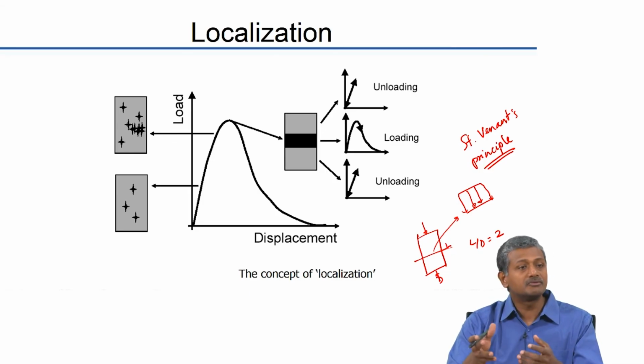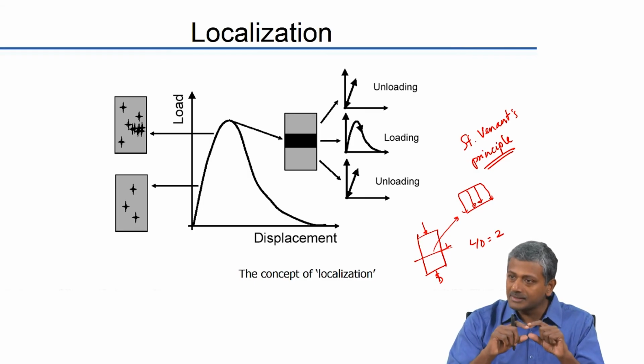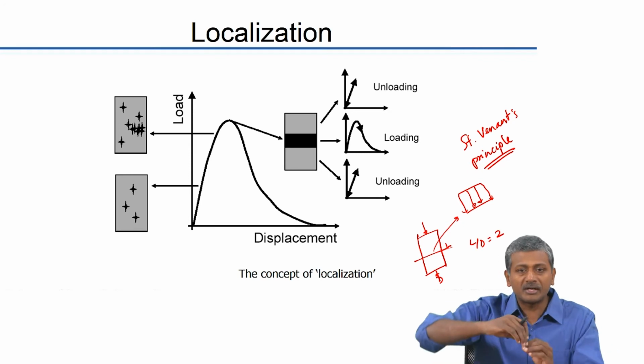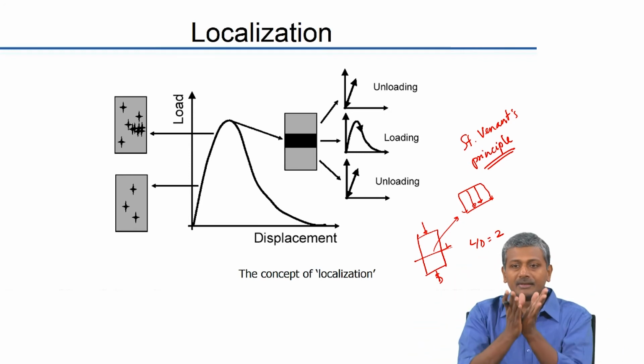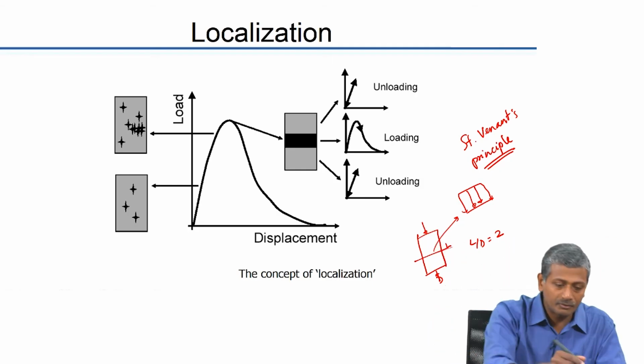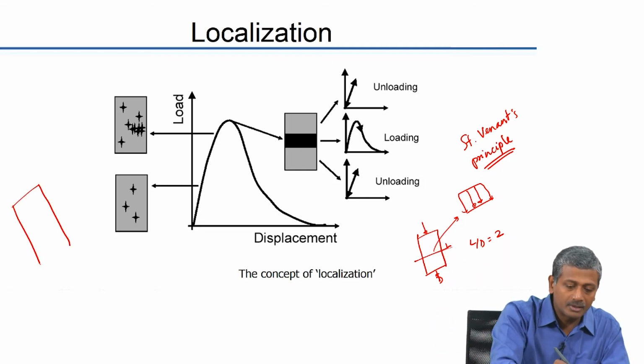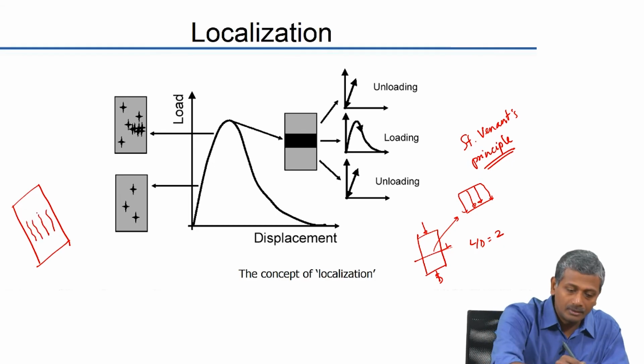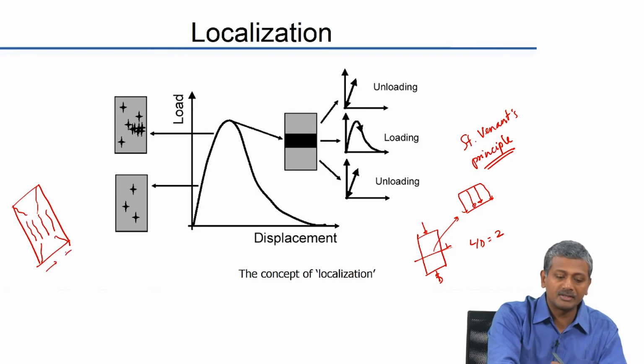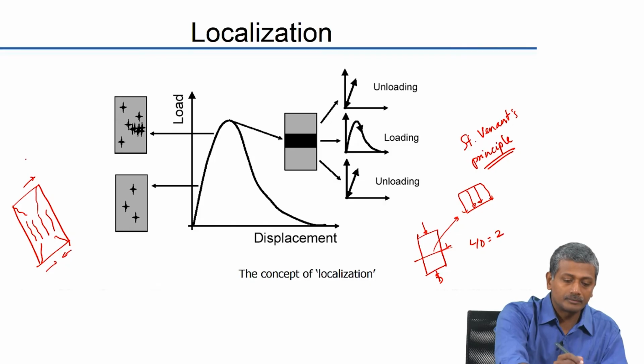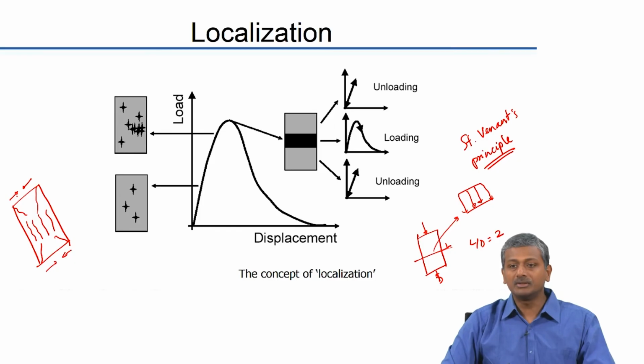Okay, and this compression is the cause for development of initiation of the cracks at the center of the cylinder, which then spread up, and because of the friction at the ends start branching off like that, right. You have seen a cylinder cracking. When a cylinder cracks, you start developing the vertical cracks in the center first, right, and then towards the top they will start branching out like that because of the friction that is present at the end. Because of the end friction, the cracks start branching out towards the edges on the top.